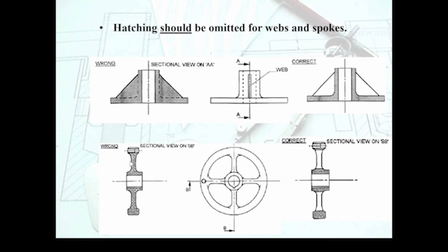So for instance, this spoke here, there is nothing to show on the inside of the spoke. These are the standard, filled material. There's no need to hatch those, and that's why this is not a good practice right here. However, around here we can see everything else.